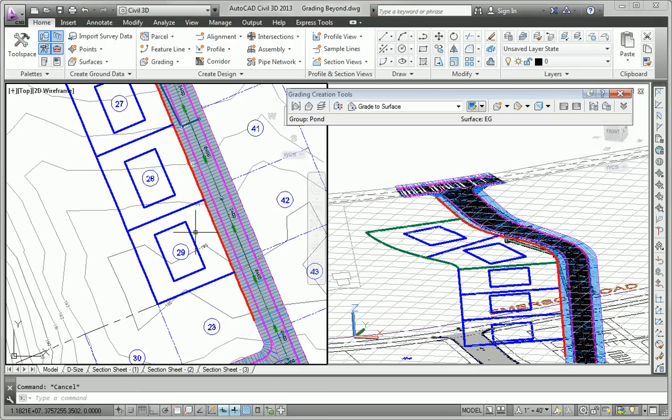Repeat that once again. I'll assume that this is the high point, but let's check it just to make sure. And we'll use quick elevation edit. That's 195, 194.5, 194.2.